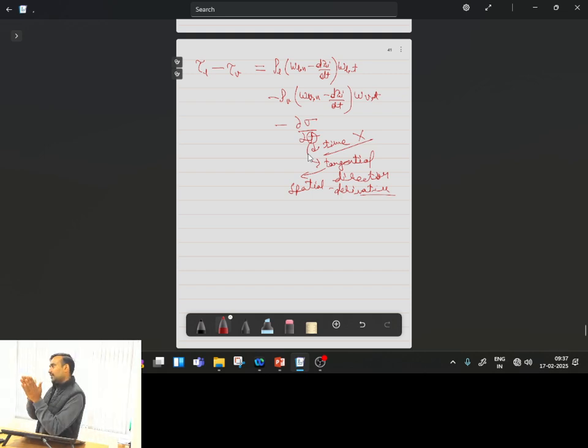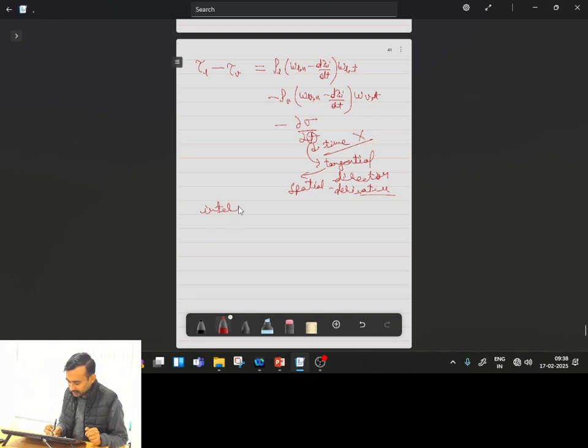One side we have liquid, the other side we have vapor. At the interface, molecules of liquid and vapor are so mixed with each other that the tangential velocity of one type of molecule will induce the same amount of tangential velocity in the other type of molecules also. So at the interface one more condition can exist, which is the condition of no slip.